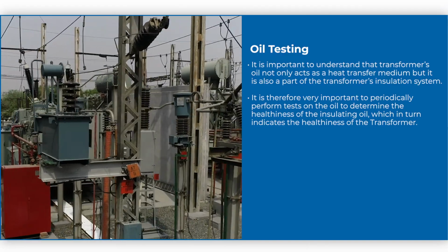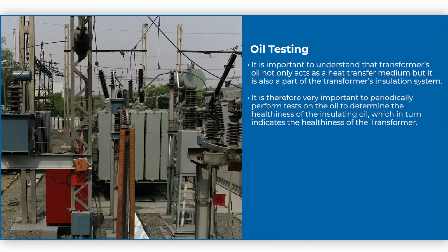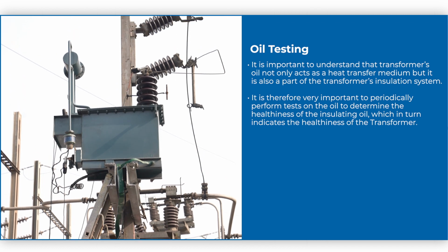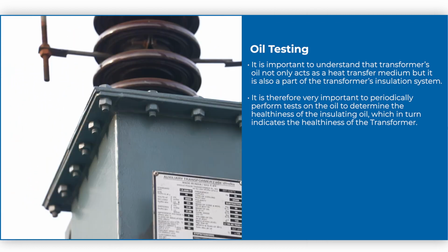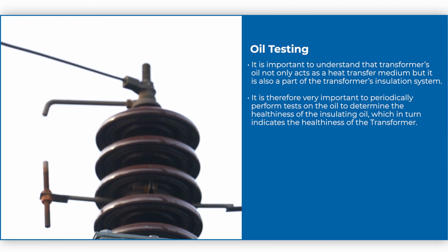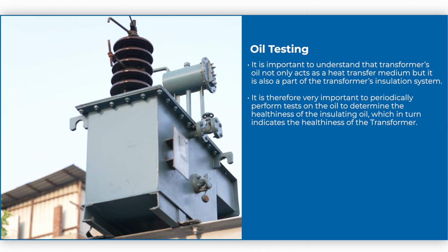Oil testing. It is important to understand that transformer oil not only acts as a heat transfer medium but it is also a part of the transformer's insulation system. It is therefore very important to periodically perform tests on the oil to determine the healthiness of the insulating oil, which in turn indicates the healthiness of the transformer.